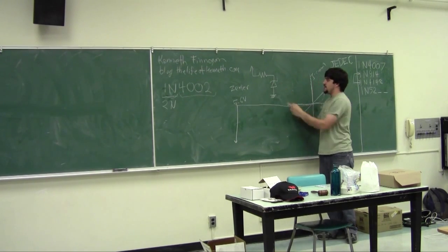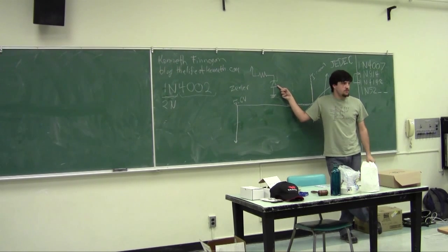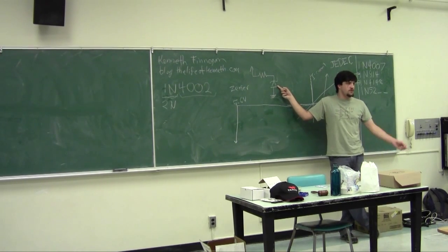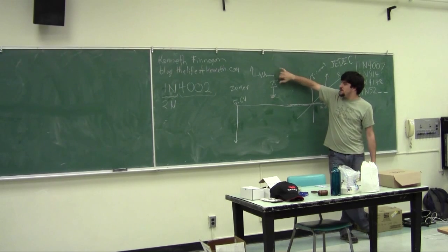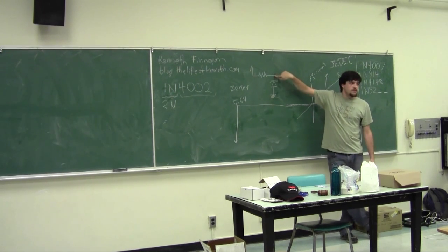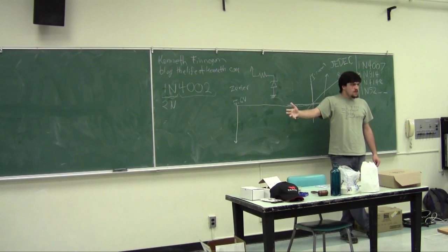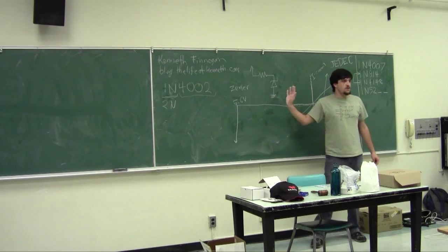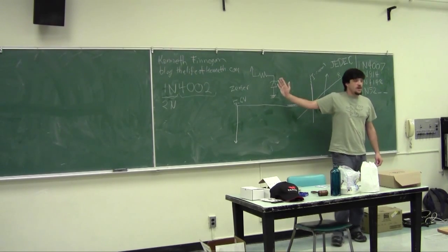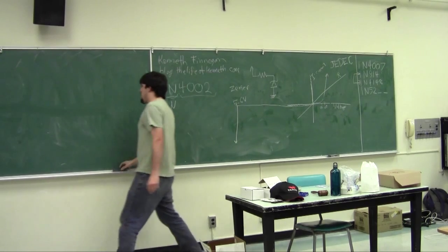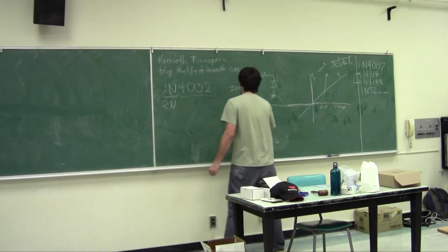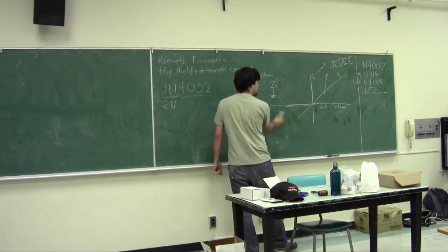and we say that the breakdown voltage of this diode is 5.6 volts, or 5 volts, or 3.3, or whatever, the voltage here, compared to here, is just always going to be 5.6 volts. Again, this may seem totally abstract at this point, but eventually you'll realize if you actually try and build something, you'll find uses for this that are nice. And that is the diode. Any questions on the diode?